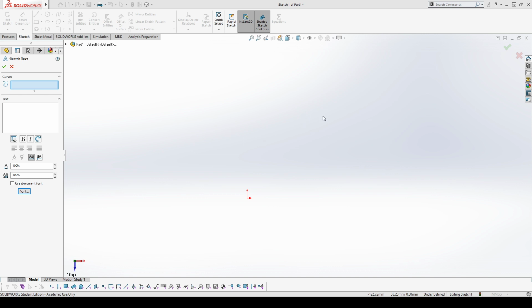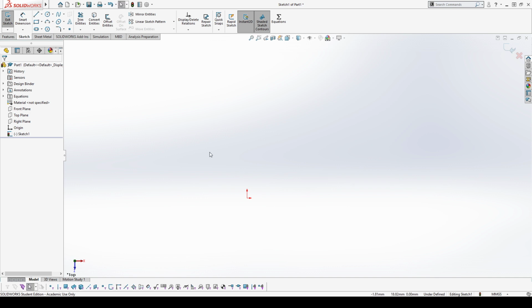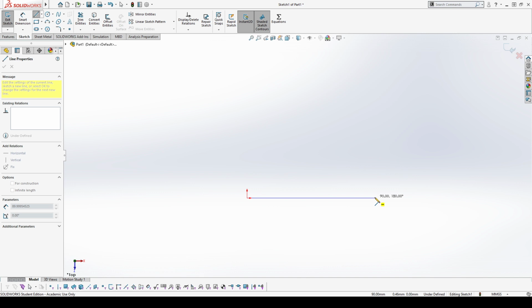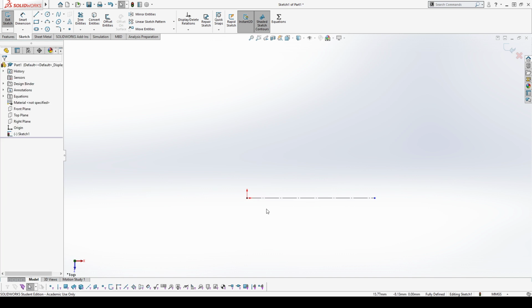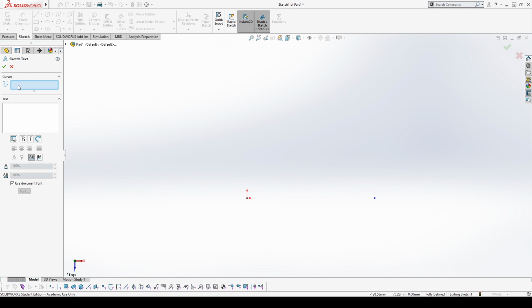We'll use Comic Sans, for example, here. Before I actually do this, I'm going to sketch in a line just to illustrate how you usually want to use text. I'm going to draw on this line. Because the line isn't actually going to be any geometry, I'm going to make it a construction line. That's usually good practice. Then I'll add in this curves drop down, click on that first, and then click on the line. Now I'm going to start typing text. It's going to follow that line.